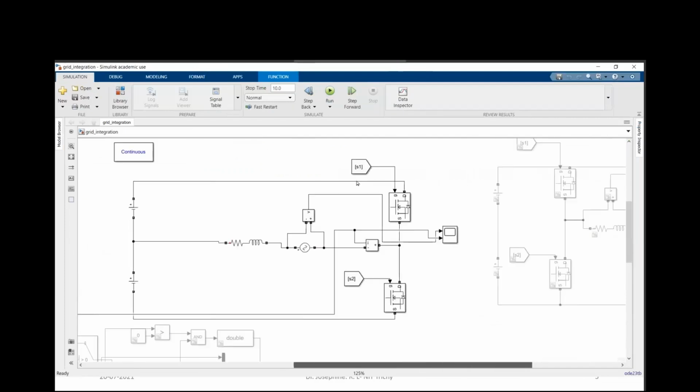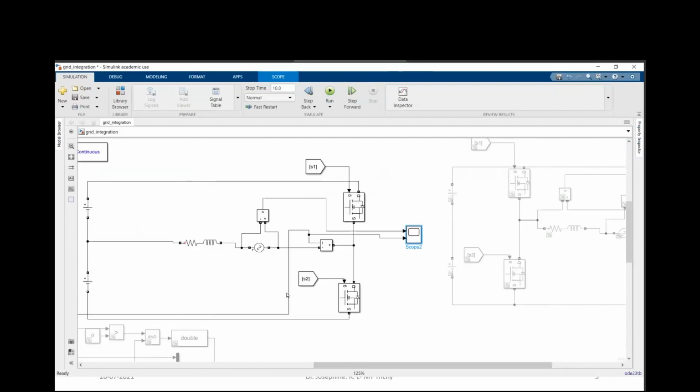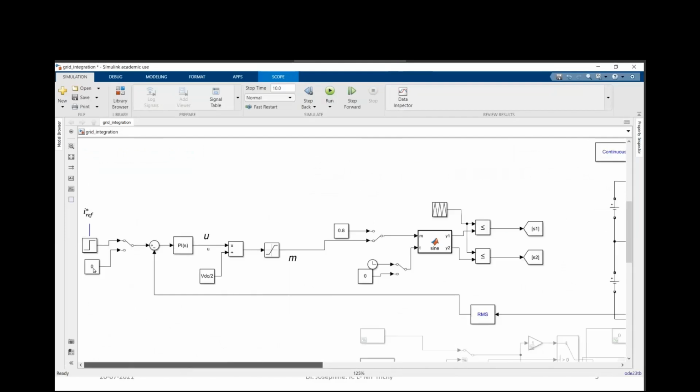So I'm switching a basic half bridge inverter, and I'm giving an RL value, the same RL values with a voltage source, and the values of these are given here. Once you trigger this, you just want to observe whether you are able to attain your required response or not. In feedback, for the current, I'm giving the feedback in RMS value. The 1000 ampere, whatever I have mentioned here, is an RMS value.